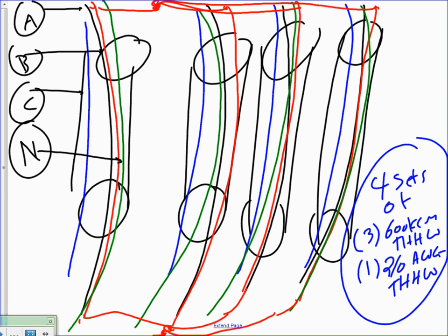Any question, guys? That's what makes a designer. I like to emphasize this: when you show phase A, it's going to phase A, phase A, phase A. How many of them? 4. They will be tied together at the end here, lining to the overcurrent protection device. From here, they will go to the transformer. Remember, there's a transformer here.